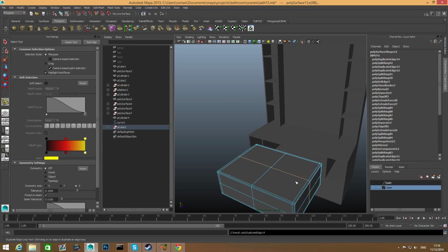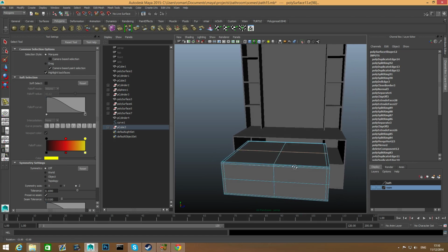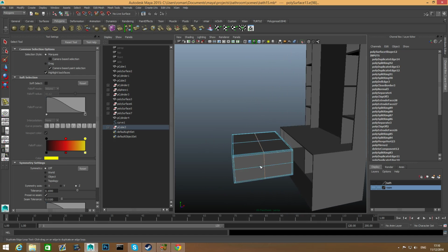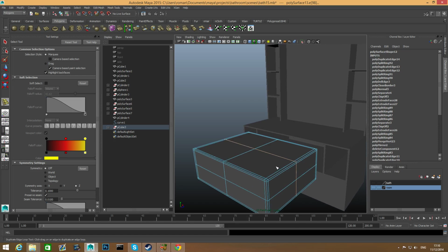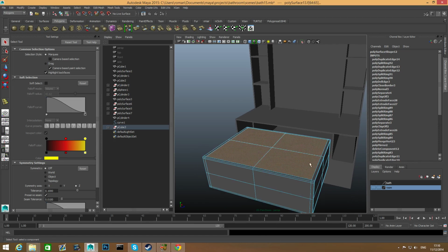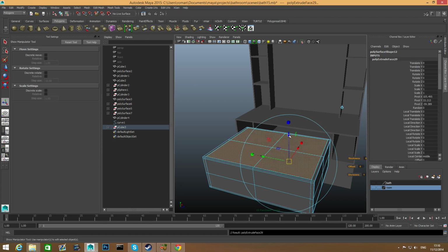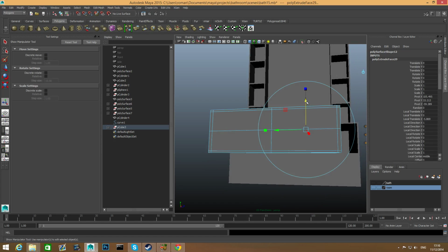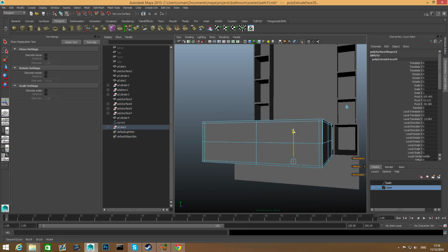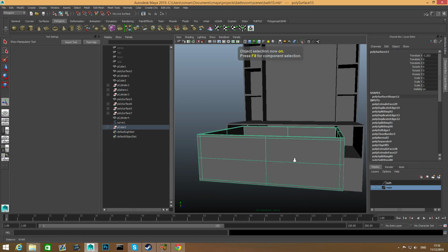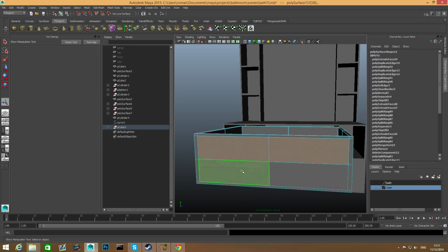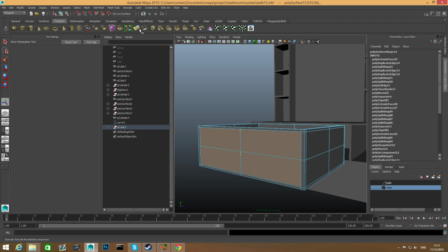Basically what I've done, I just added something like maintaining edges, but it's not really the purpose of it, because this feature isn't going to be smooth preview. It's just borders in order for me to grab those four and still have some thickness here. So I can extrude those down, make sure that they are extruded downwards that way, and then lift them up a little bit. Okay, press F8, and then I will be able also to grab these four faces and extrude them once.